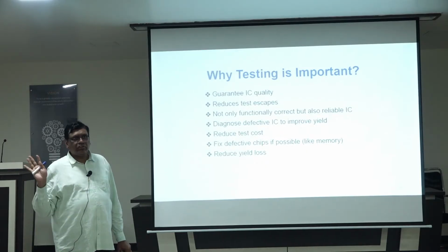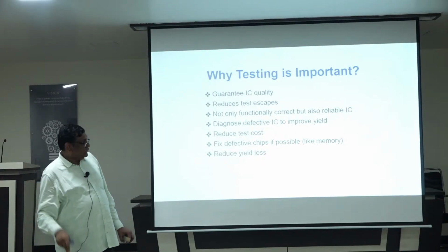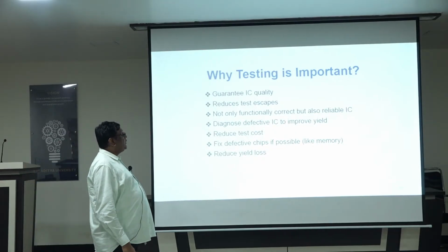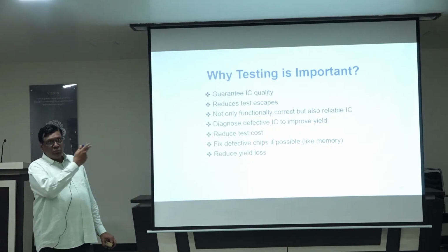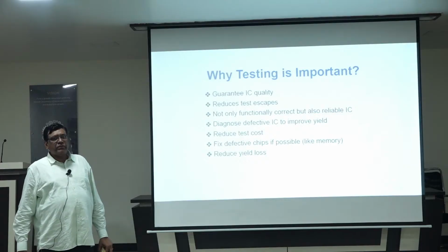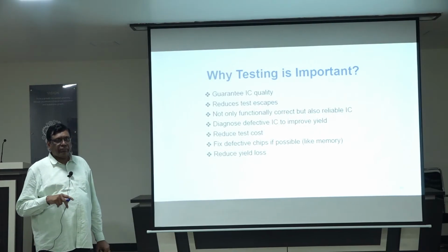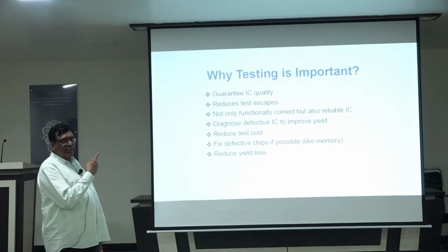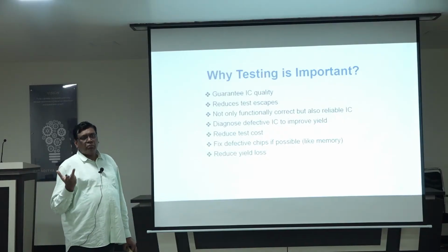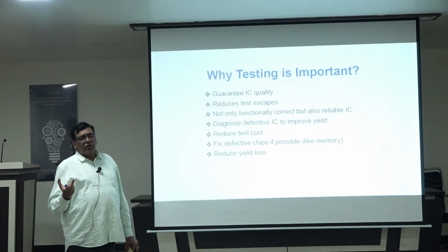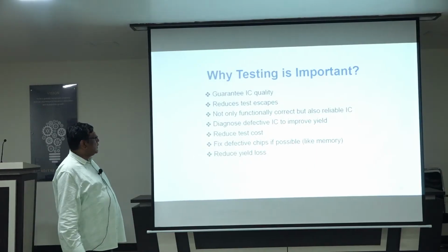Otherwise they will not release it into the market. They will throw it off. So that much importance is there. Reduce test escapes. Just now we discussed test escapes. That is more costly actually. That means a defect is there, still it is passing the test. That should not happen. That is very dangerous. These test escapes only will come to the customer as malfunctioning ICs or malfunctioning phones. So that is the cause of that.